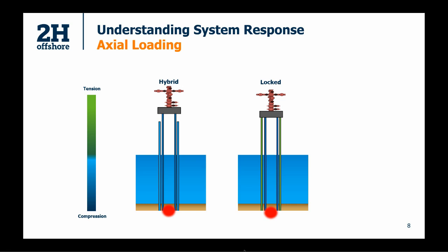And in the case where you have very high temperatures in the well, it's possible to put the conductor from a high level of compression into tension. And in the case where you've maybe got temperature but it's not as onerous, then you would still see the conductor have a lot less compression at the end of that than it did at the start.